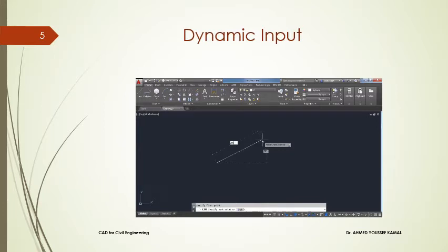So after entering this distance, press tab, and when you do this, you'll see that a lock icon appears with this distance box, and now the selection moves on to angle. Now you can enter angle about which you want to incline this line with respect to x-axis. So let's enter 30 degrees. You don't need to enter any symbol for degrees, and press enter. As soon as you do this, you'll see that we have a line with a length of 200 units and which is inclined to an angle of 30 degrees with respect to positive direction of x-axis. Now in this way you can continue making this line. Let's press enter again to exit this command.